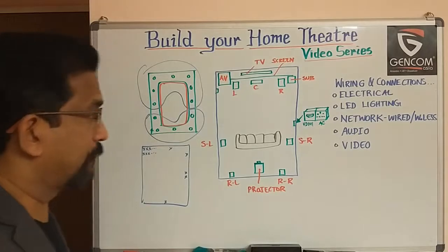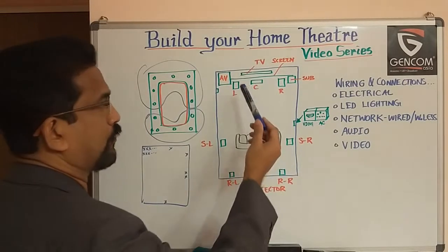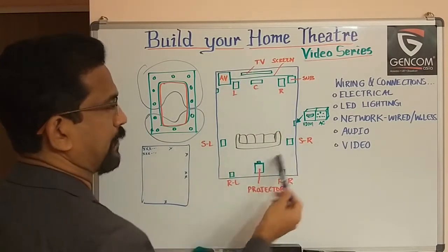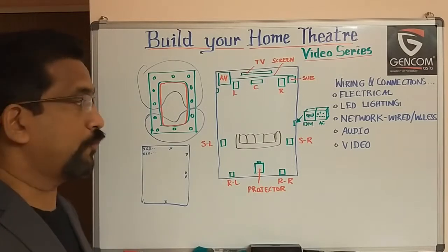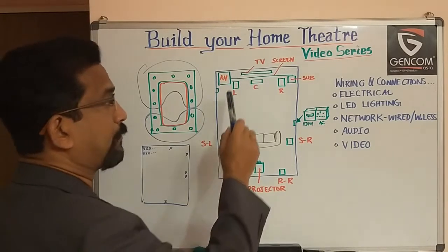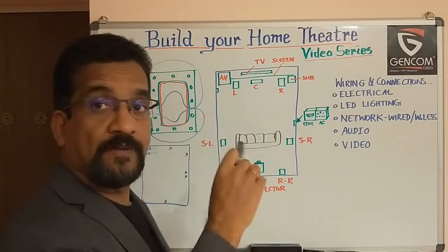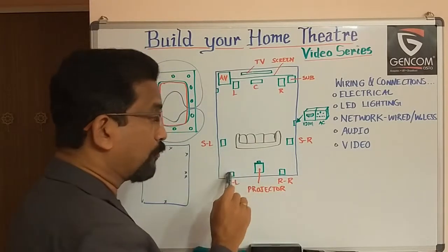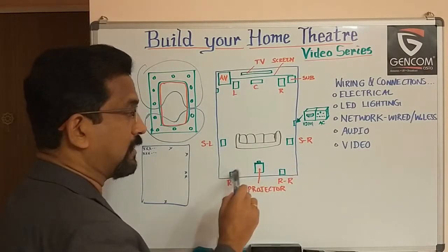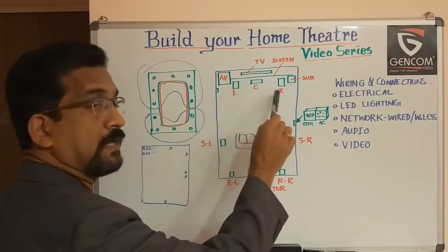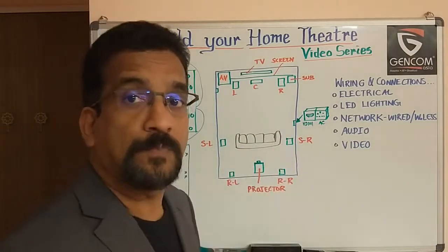Coming to audio cable. For audio cable, as you know, you will have to connect all the speakers through an audio cable, because the power is coming from an AV receiver. These are all non-powered speakers, right? All these non-powered speakers have to be run through a speaker cable.